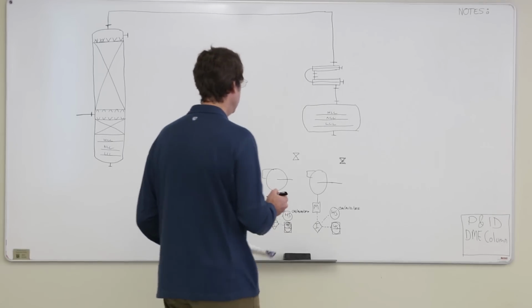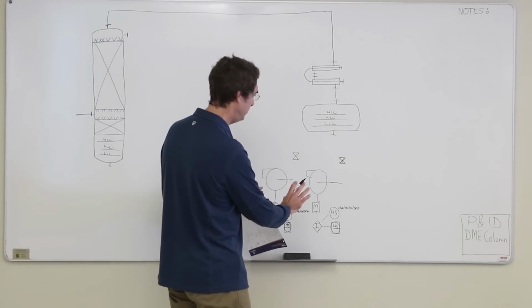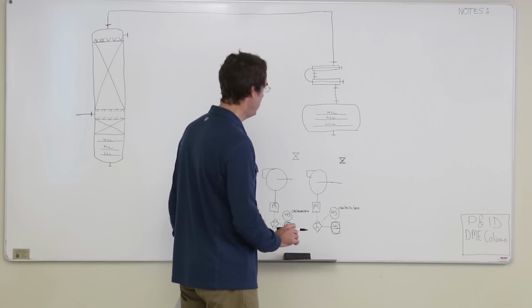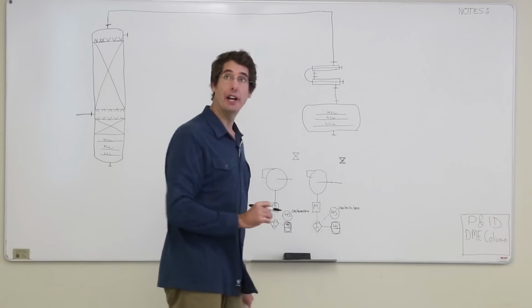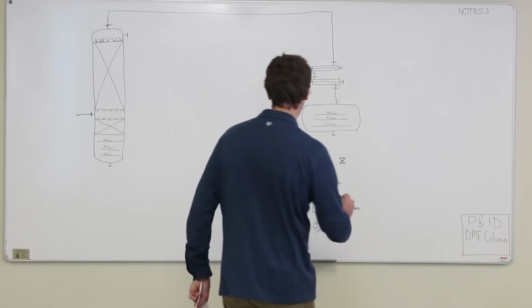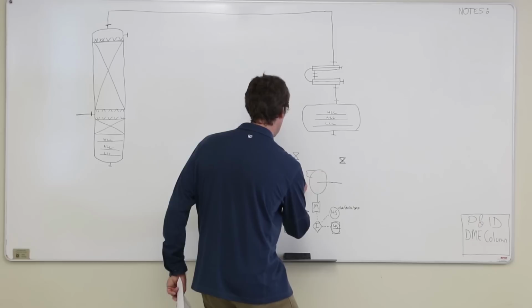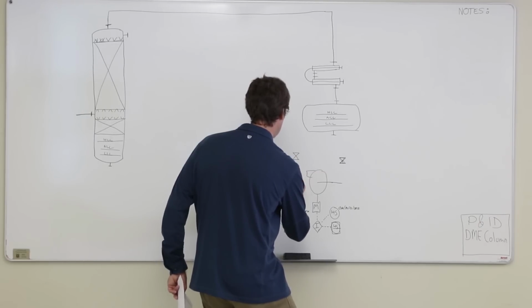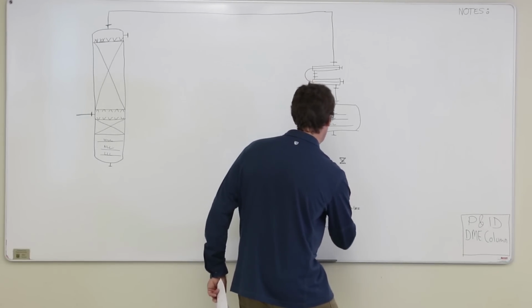So we've got our pump isolation valves here. The next thing we need is, let's just draw the piping. Usually there's a reducer right on the inlet to the pump, just because the pumps are almost always one size smaller than your line sizes.